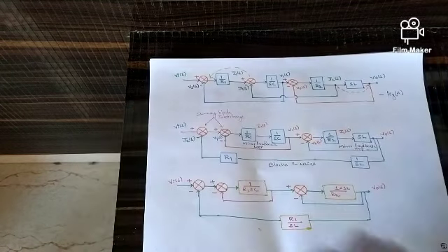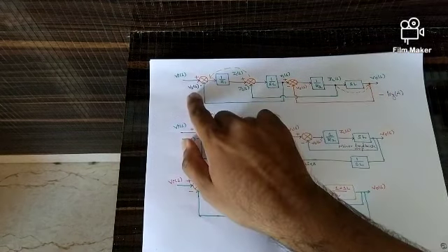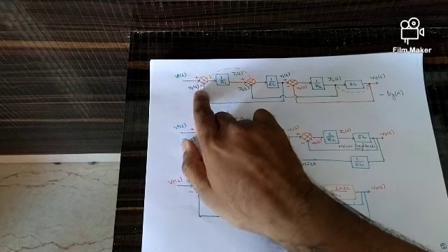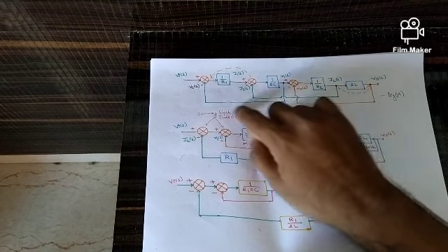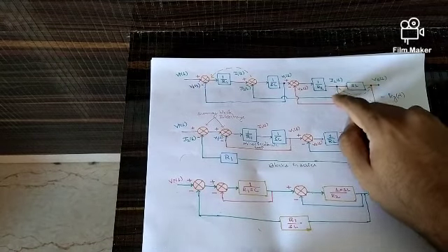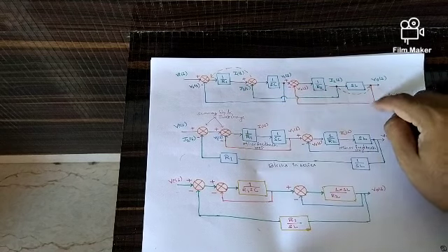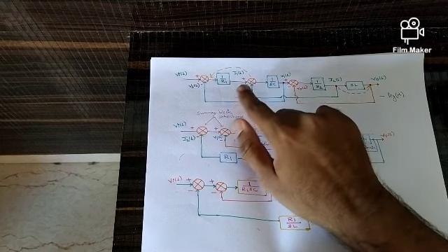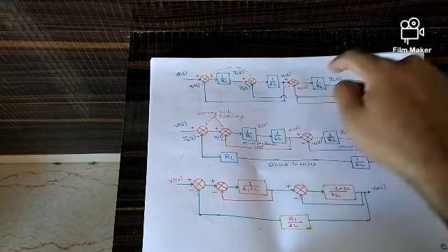So what we have here is we have just combined all the block diagrams, and wherever there is a negative V1 of S, there is a feedback symbol. As you see, V1 of S exists at this point, so I am writing a feedback to the summer. Again, I2 of S is fed back from this point to the summer. Again, V0 of S is fed back to this summer. In between we have different gains: 1 by R1, 1 by SC, 1 by R2 and SL.